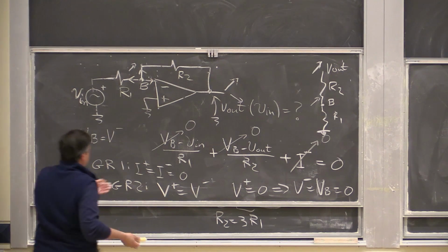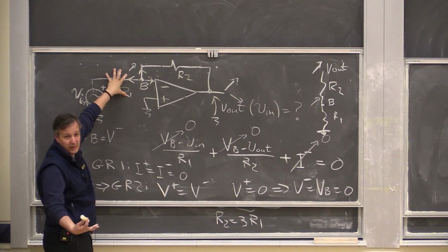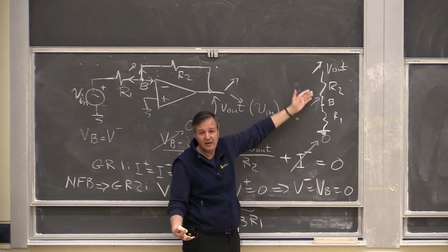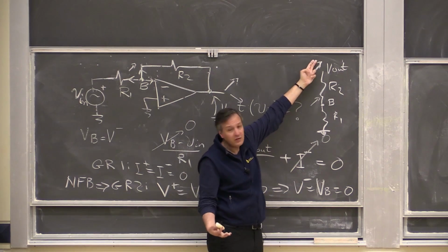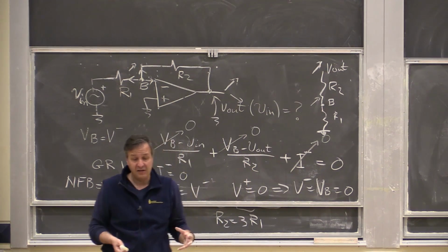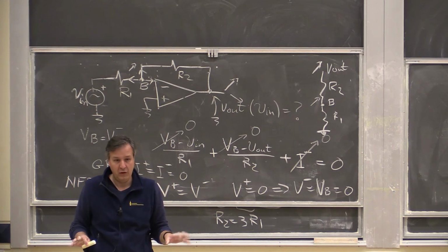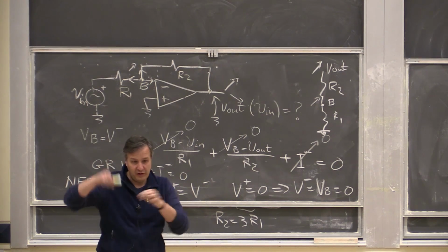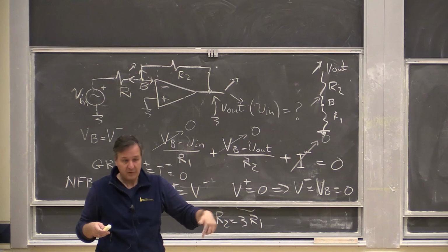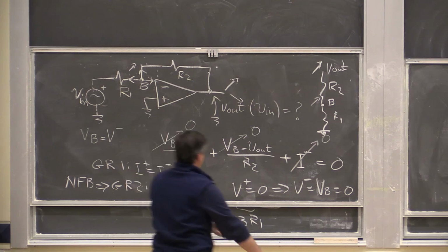Simply because if you see this scenario, whatever I have here, some equivalent resistor capacitor, I will always get some form of a divider here. So if I'm increasing the output voltage, this node will have to increase. Now, if I have an active block, like another amplifier, that we're going to do shortly, this is not true. But as a quick inspection, if you don't want to move around the circuit, boom, you have a circuit with a resistor in the feedback, you know it has to be hooked up to the negative terminal. Okay.